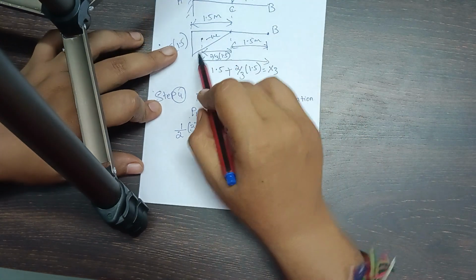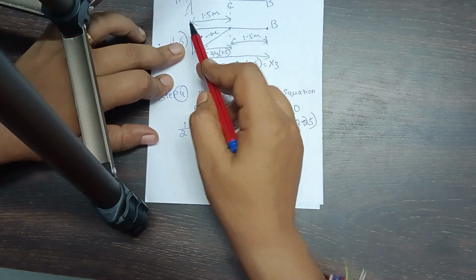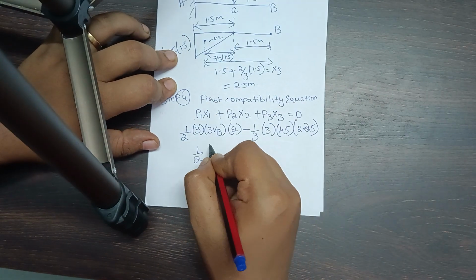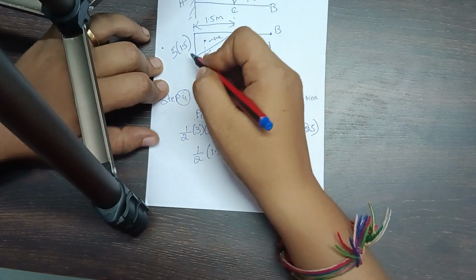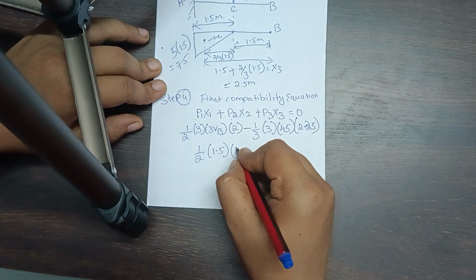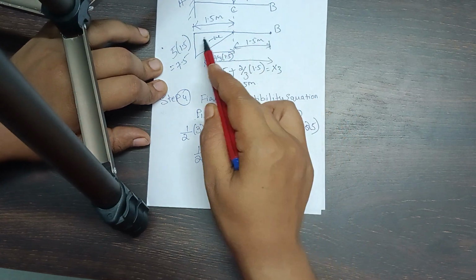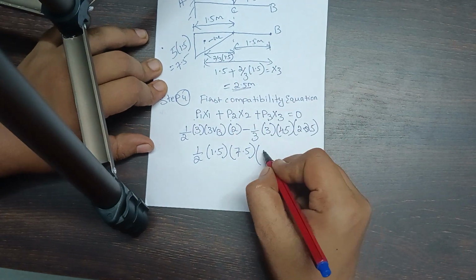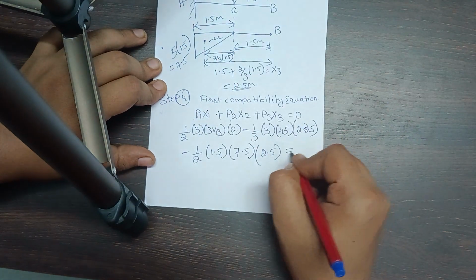Next, you have the third elastic load diagram here, where P3 is the area of this triangle. So the area of this triangle is equal to half into base distance 1.5 into height 5 into 1.5. So it is 7.5, into x3, the distance from B to this centroid. So we have got it as 2.5. It is a negative value because it is a negative variation.